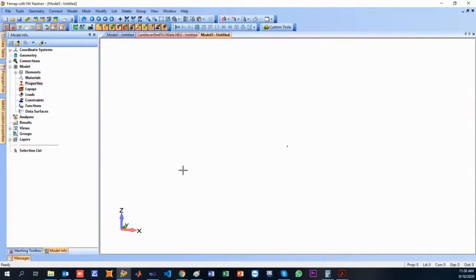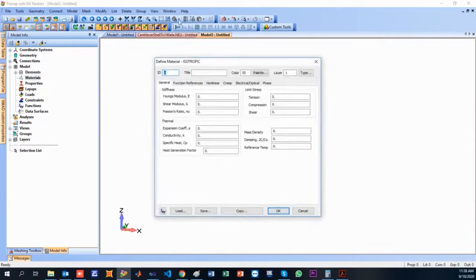All right, this is our software again. Let's start drawing our model. The first thing, of course, we need to create new material. We will call this C45, 30 gigapascal, and of course, this is 45 megapascal, Poisson ratio 0.2. I will not take into consideration the self-weight, given the fact that my calculations are all based on just a single load P which was applied. And of course I will create my steel,